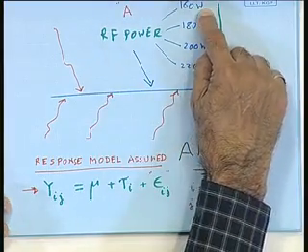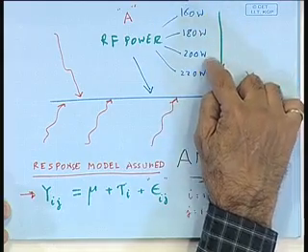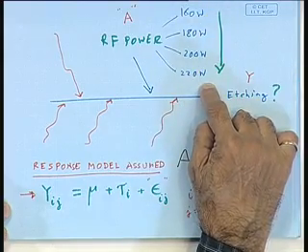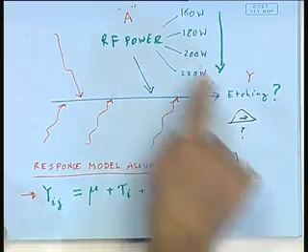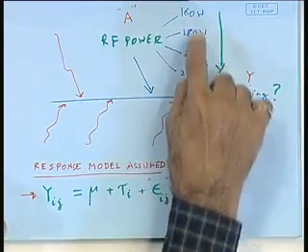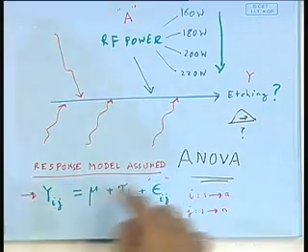So changing RF power, this is initially what we started out to do. We changed the treatment levels. Look at the picture here. We looked at 160 watt. Then we changed the setting to 180. Then we looked at 200. Then we looked at 220. And each time we did this, we kept looking at our etching. And of course, we replicated the trials. Each time the treatment was changed, we replicated the trials, and I ended up with my data there.